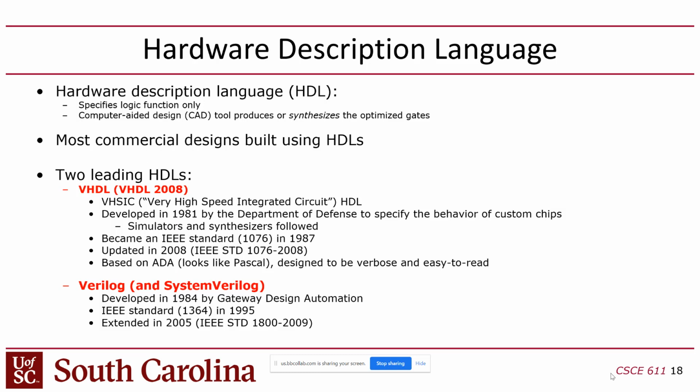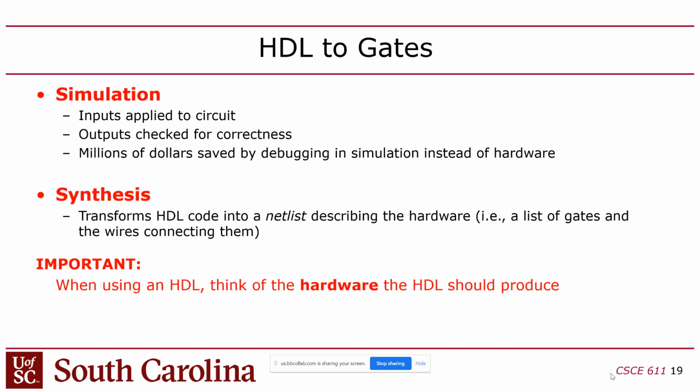Whereas Verilog actually came out of industry, from a company called Gateway Design Automation, which was eventually bought by Synopsys. Verilog looks more like Python, Java, or C. It's case sensitive. It's more sparse, and it relies more on comments because if you don't comment it, it's harder to read. It's not self-documenting. So I think everyone should be more comfortable. But once you learn one, it's not hard to learn the other, because they both have the same kind of semantics. They just have a different syntax.